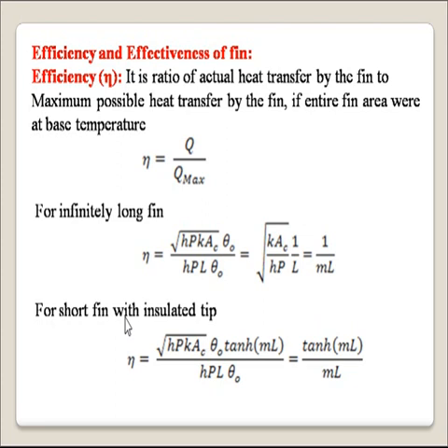First we'll see efficiency, which is simply the ratio of actual heat transfer by the fin to the maximum possible heat transfer by the fin if the entire fin area were maintained at base temperature. Mathematically, efficiency is equal to the ratio of actual heat transfer rate Q to the maximum possible heat transfer, Q max.